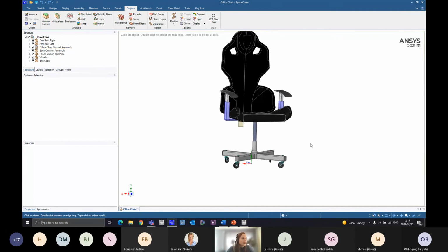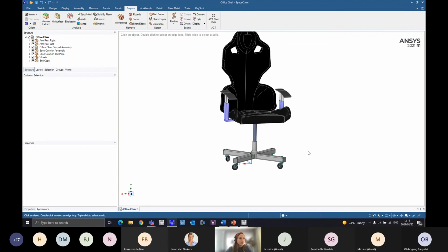In that case, you will suppress those components. In other cases, it's also possible to suppress components that you feel are not relevant to your study. So that's all good. I think it's always useful to make your model as small and efficient as possible. So selecting your boundary, I don't want to say boundary conditions, but like your battery limit of your model, is up to you, and that is up to your engineering judgment.